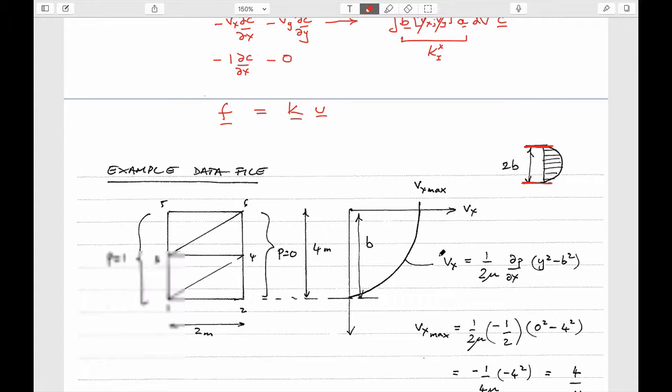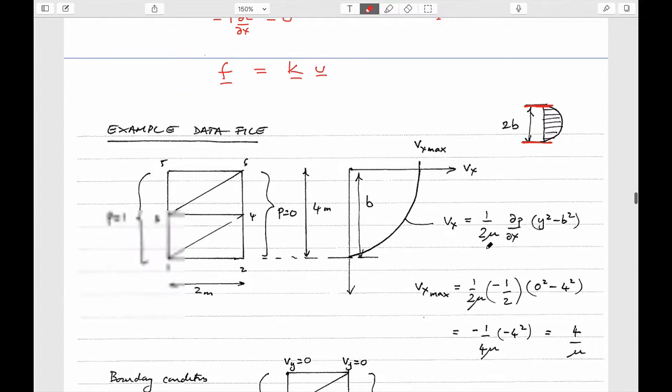Then the solution to that system of equations is pretty straightforward. You get a parabolic velocity profile where the fastest flow is in the middle, and the slowest flow is at 0 where it contacts the plate, where you can imagine it as being attached to the static plate, so the velocity is 0.